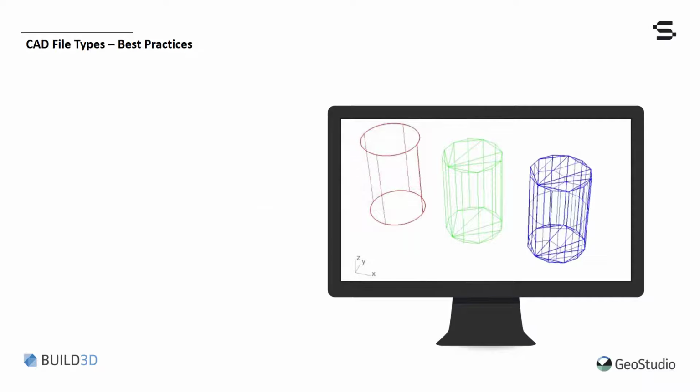First, let's talk about the different format types that can be exported from CAD software. When importing in the STP or IGES format as a solid, it is best to ensure that the body is a parametric representation. For example, consider these three cylinders. All three cylinders can be saved to the STP file format. However, each have been created in a different way and will behave differently when imported into Build 3D.